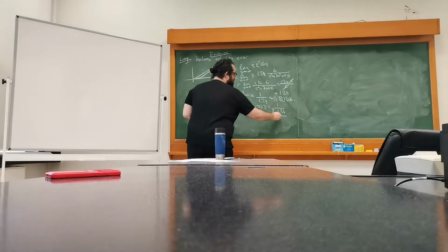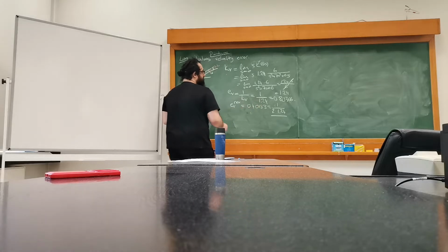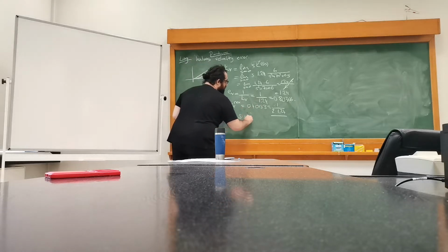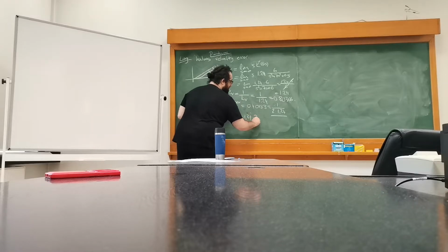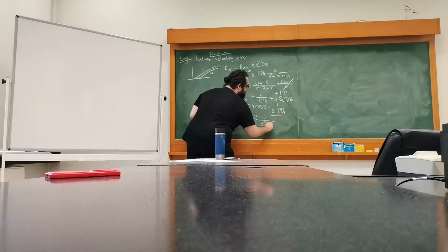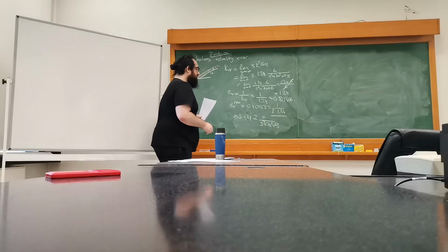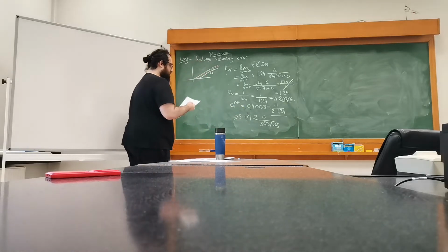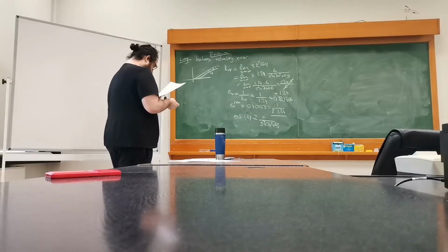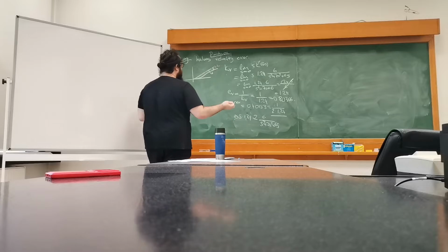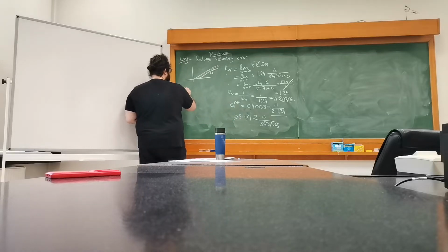So this should be the gain that I add to the system. So instead of having s times 1.24, I want to have times 2 times 6 divided by s cubed plus 7s squared plus 6s. If I calculate this limit, then I see that I get 0.4 as the velocity error. Therefore, I can combine the controllers or I can leave them separate, so it's really up to you.